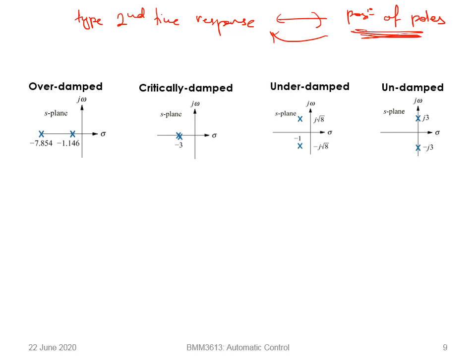So then again, how do we change the position of the poles? As I've said just now, the position of the poles can only be changed if you change the parameters of your system. So let's start. For example, if we have our poles in this position, right? We have two distinct poles, both of which are real. Because the sigma axis represents the decay, it has decay, but it has no undulation.